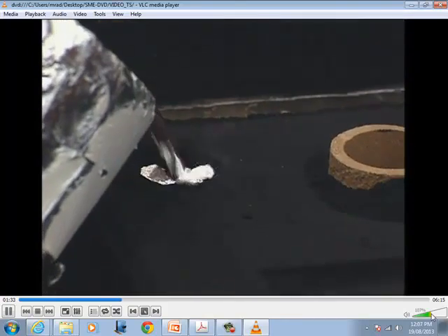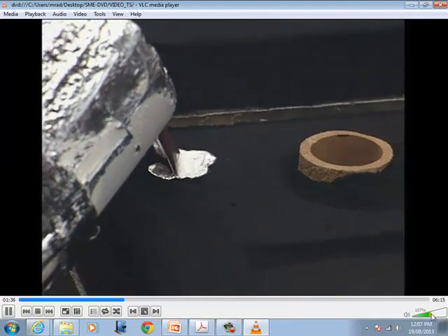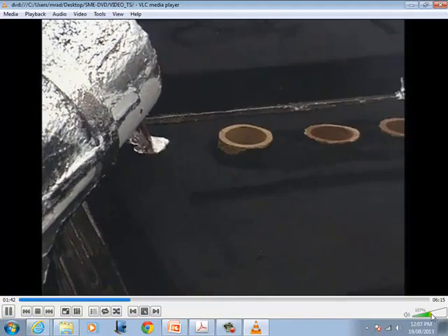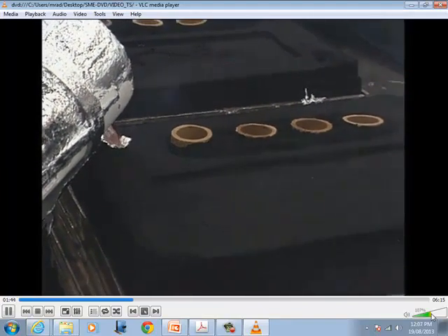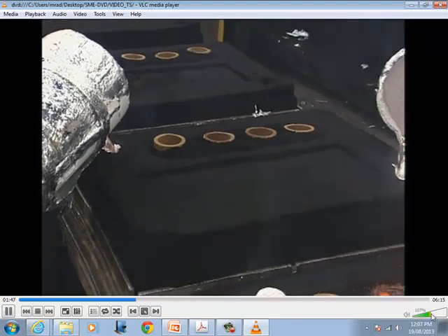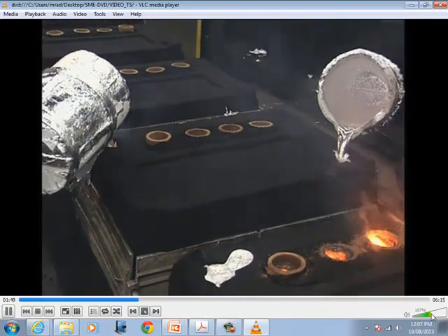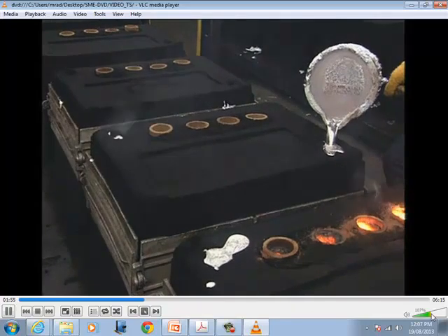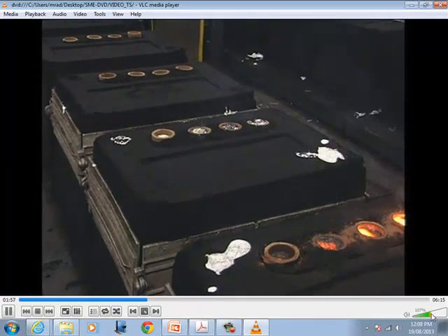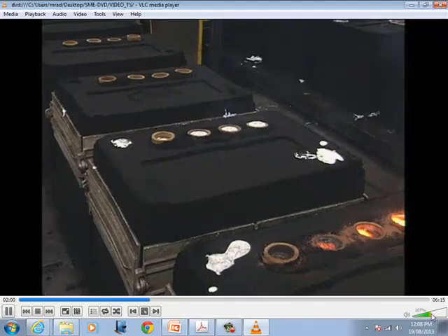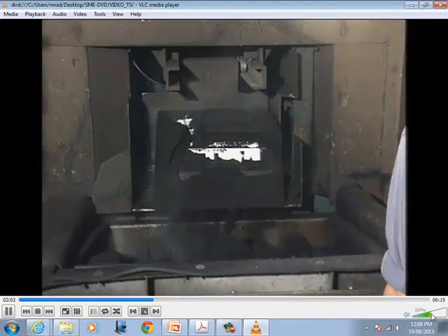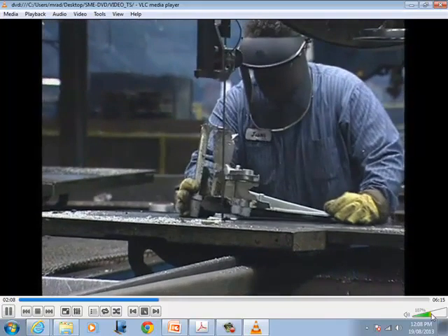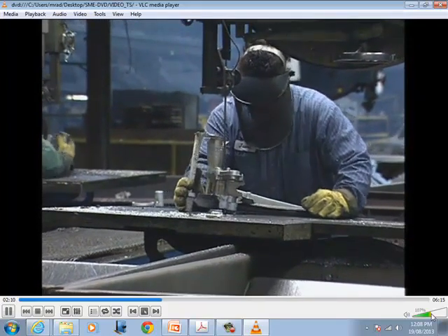In casting, metal flows from the pouring basin through the sprue, runners, and gates to the mold cavity. Vent holes formed in the cope and drag, and often in the cores, permit trapped gases to escape. After filling the mold, the metal enters the riser or risers, which serve as reservoirs of excess metal to compensate for metal shrinkage during solidification. Once cooled, the casting is removed from the mold, and the metal in the runners and risers separated from the casting for remelting.